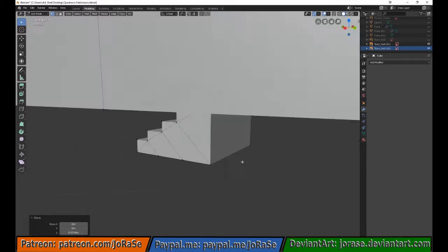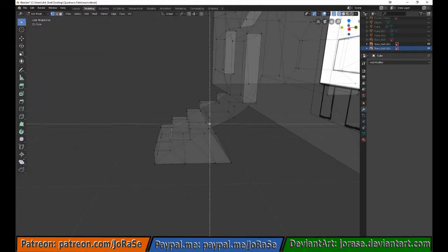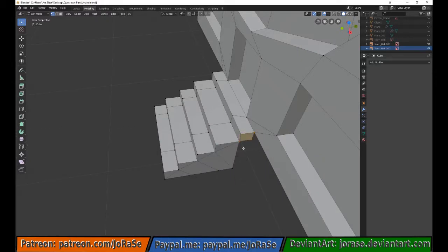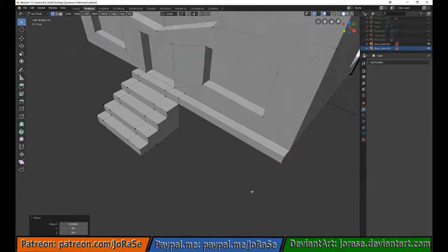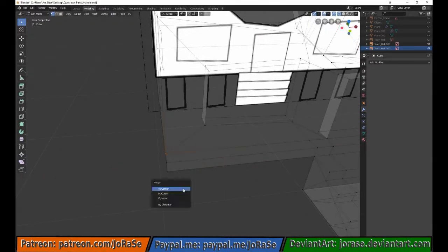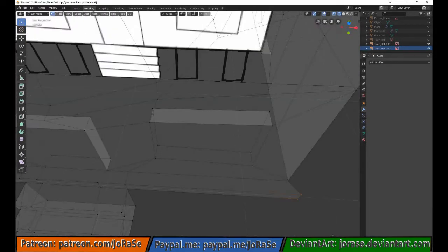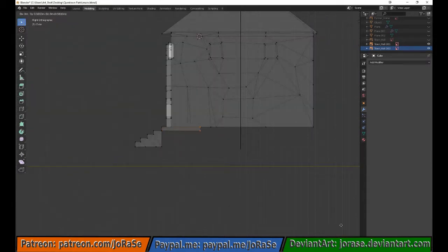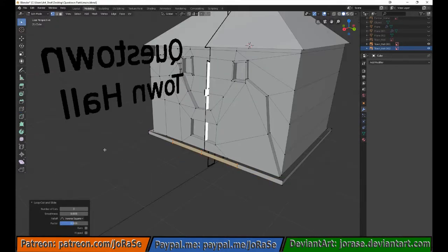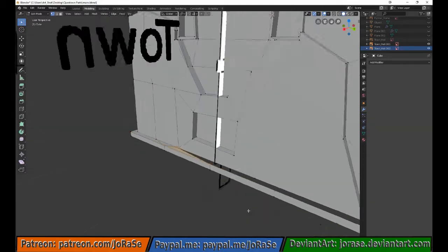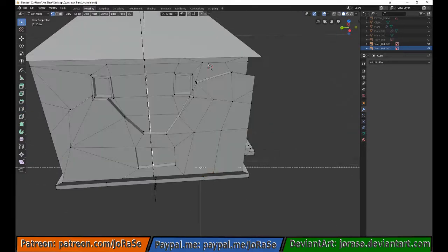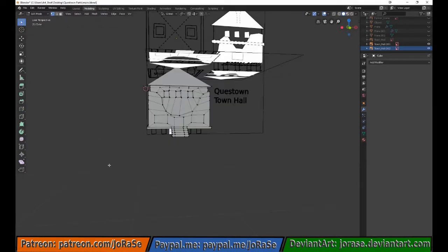Now, I realize that I kind of want to have an extended floor look to it. So that's what we're doing here. Get that on both sides here. Just stretch that a little bit more there, and now to extrude it all the way back. There we go. Fill in these faces after making sure we have enough vertices, of course. And same thing on the other side here.